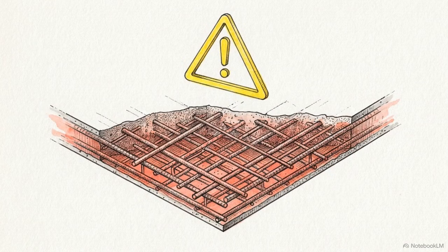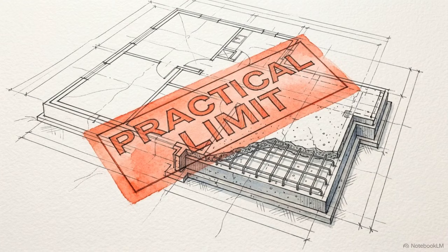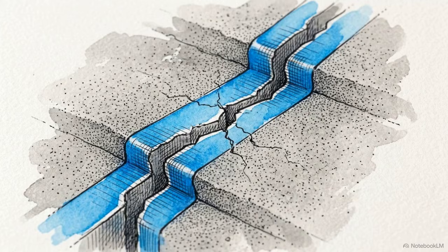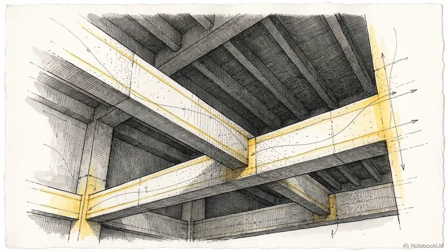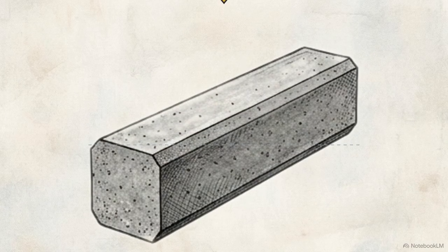While slabs are theoretically capped at a 4% maximum, their massive cross-sections mean they are generally lightly reinforced, and this upper limit is rarely approached in practice. In footings and slabs, minimum reinforcement provides an environmental shield, preventing the concrete from tearing itself apart. In structural beams, the primary threat profile shifts from environmental shrinkage to pure flexural tension.